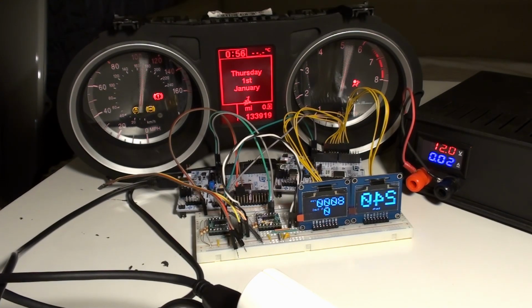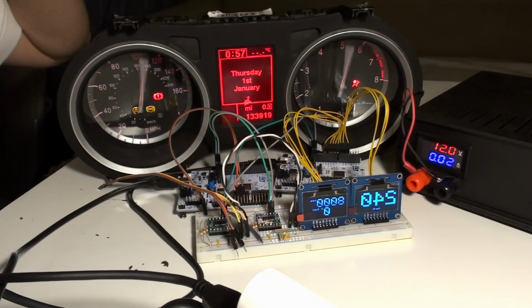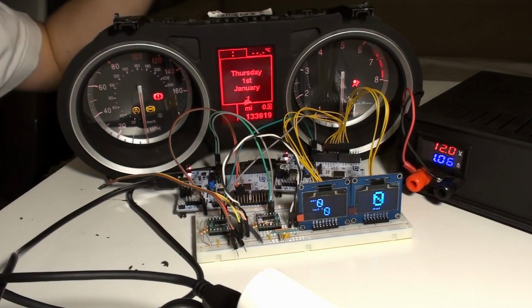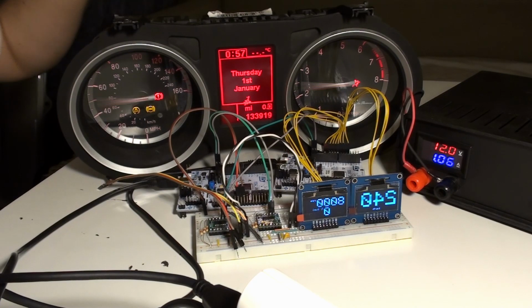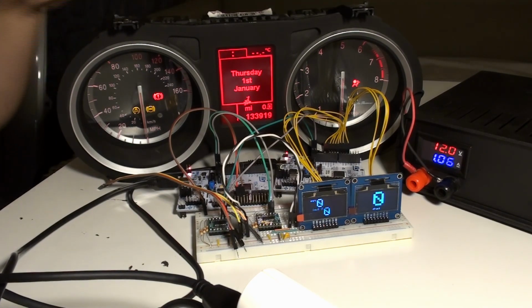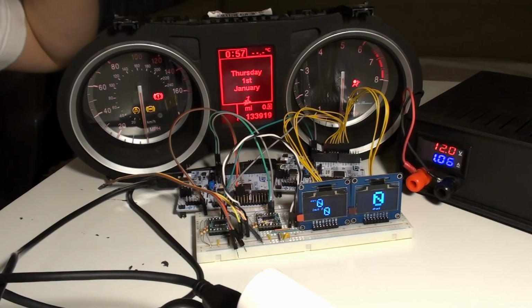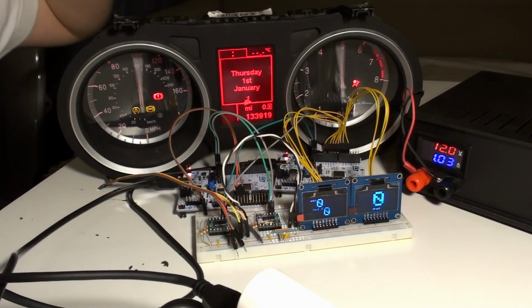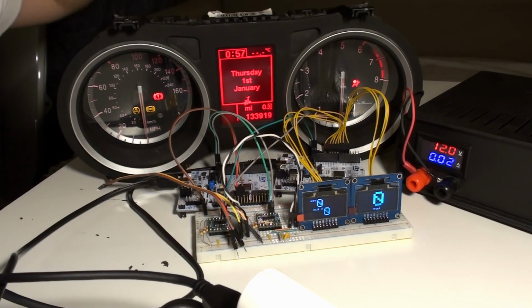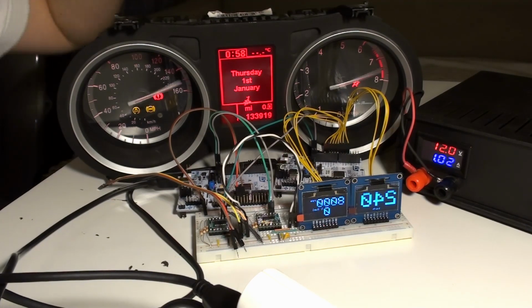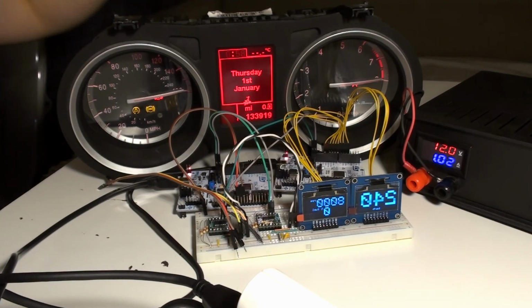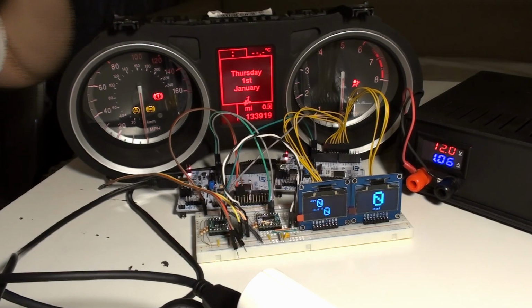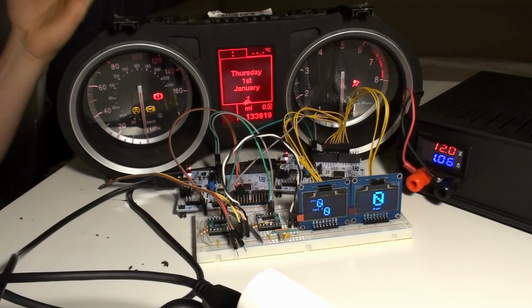Yeah. What's left to do in this project? First I have to do some wake-up concept, because the transceivers here are capable of being connected just to the permanent 12 volts, and then if there's any traffic on the CAN bus, they can detect it and set an enable pin for the power supply section of the device. So that's how it can wake up the device without having the intermittent or ignition 12 volts signal. Yeah, so that's the wake-up concept.